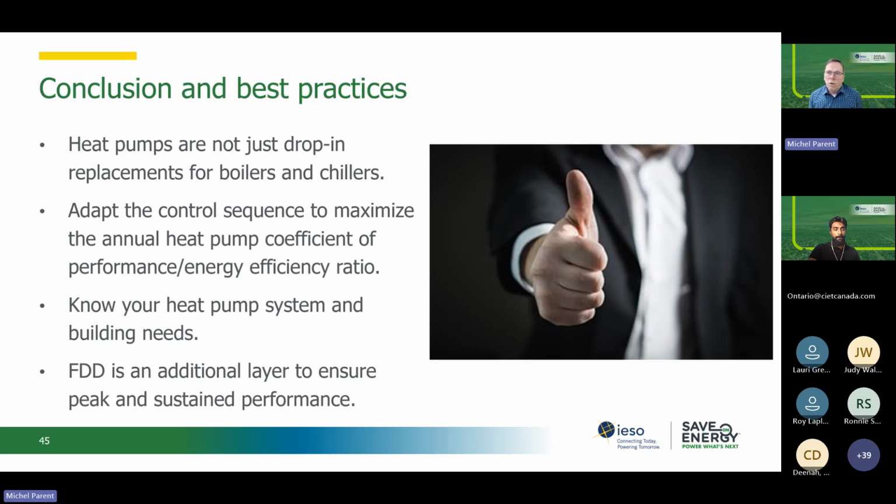Well, windows in terms of heating, hi David, as you know, they are the largest portion of the building envelope heating load. So typically, I'm trying to remember here, maybe 40% of your heat goes out through windows. So obviously, if you can improve the windows to reduce the load in the winter for the heat pumps, it's a huge deal because it's your number one heat loss element.